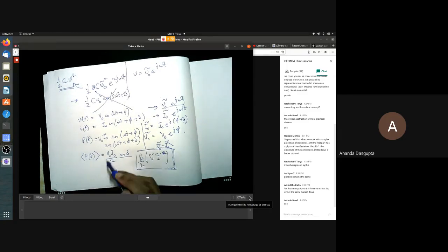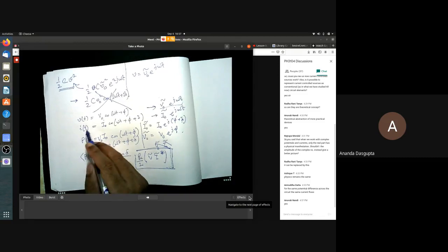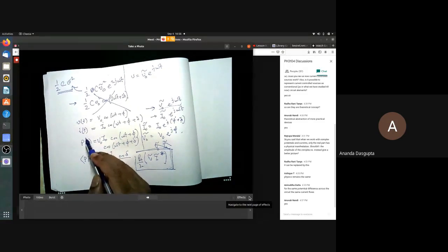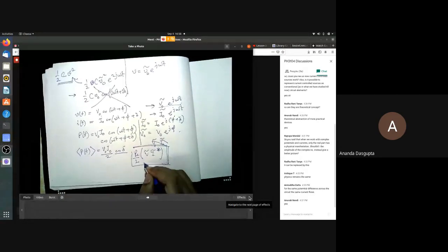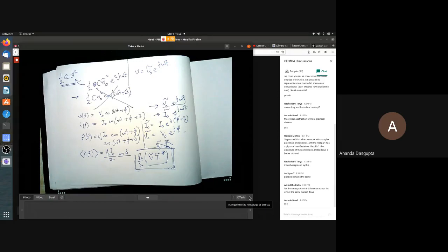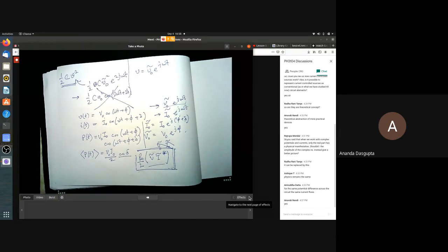All I'm saying is you can mimic the calculation that you should really do. Take the actual instantaneous voltage and instantaneous current, multiply and average. You can shortcut the whole process by simply multiplying the voltage by the conjugate of the current, taking the real part and dividing by 2. That does the job just as well. Okay. So the point is, if you want to do nonlinear things, if you know the shortcut to use, you can use that. But if you don't, you have to take the real part first and work it out. It's always a real part. That is a real calculation always.